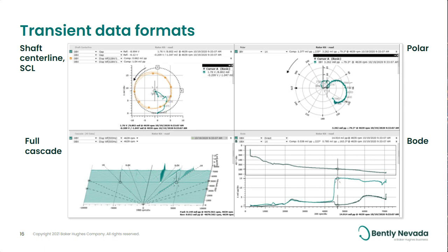One really neat feature about this particular shaft centerline plot is that you can see an orbit superimposed upon it. And again, I was talking about how we were using rotor kit data and how we had an oil whirl bearing on the outboard end and a spring-loaded preload frame that we could basically center the shaft in that bearing so that it was really susceptible to whirl. And you can see a very, very nice whirl orbit going on, superimposed on that shaft centerline. You can kind of see where we moved it, so forth.